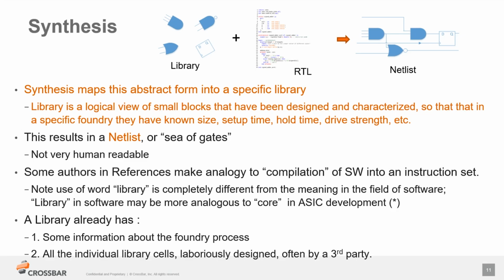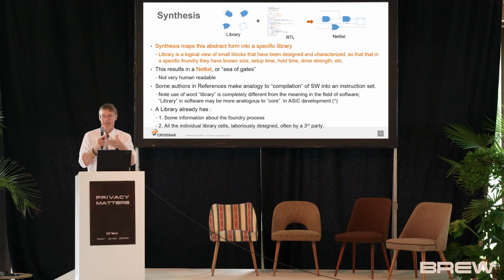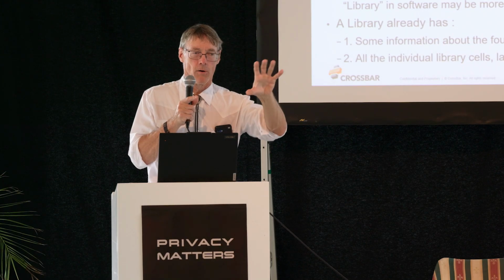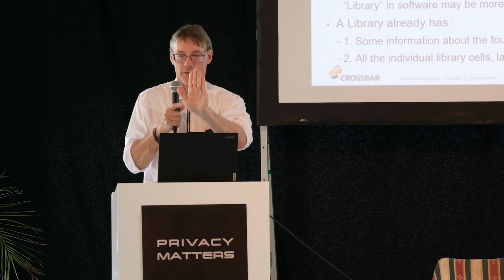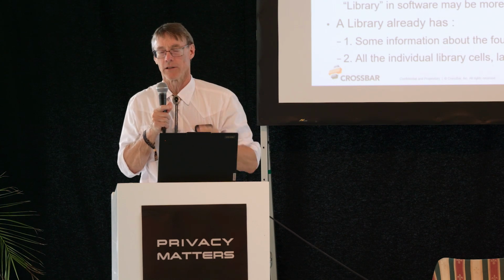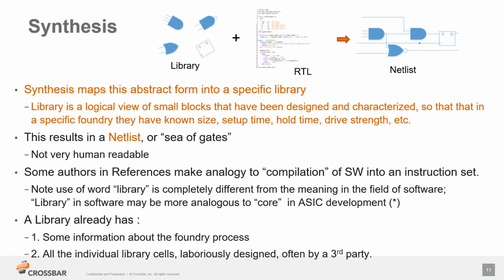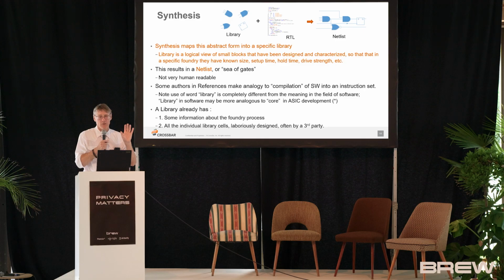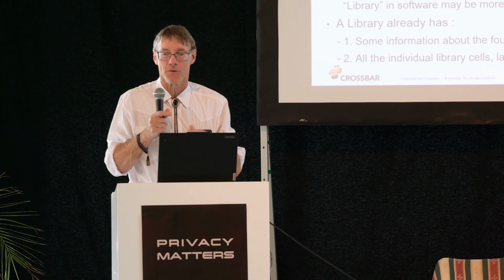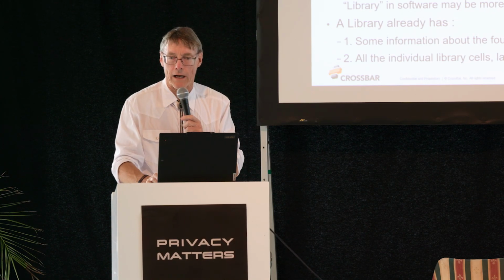Okay, so when you start to build the logic, you take that and try to map it into AND gates, NAND gates, NOR gates, and so on, and crucially, flip-flops, synchronizing elements that have a clock. So it's generally a cloud of combinational logic and then some synchronization, and then more combinational logic and synchronization. So it tries to map this concurrent programming language into these elements. Well, these elements are the beginnings of what you can construct on the wafer. So this has a little bit of proprietary information of the foundry, for example, just what are the cells that they support, but it doesn't have anything really physical about their factory and process.